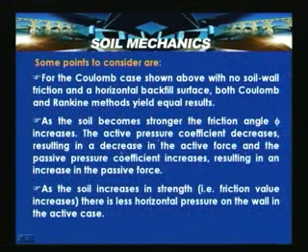As the soil becomes stronger, that means denser, the friction angle increases. So the active pressure coefficient decreases, resulting in a decrease in the active force, and the passive pressure coefficient increases, resulting in an increase in the passive force. So this we need to note. As the soil increases in strength, that is the friction value increases, there is less horizontal pressure on the wall in the active case. This indicates that you need to compact the soil so that it exerts less pressure in the active case.